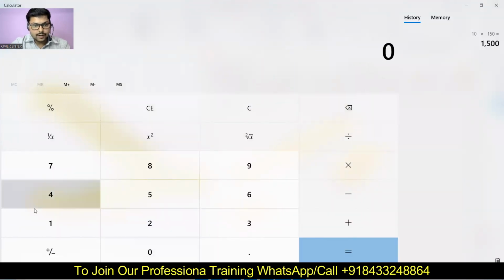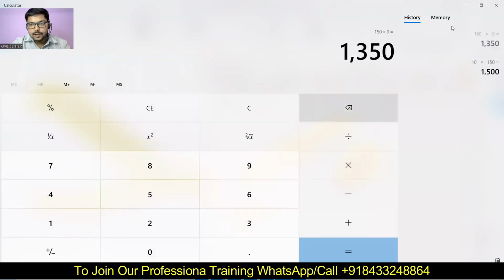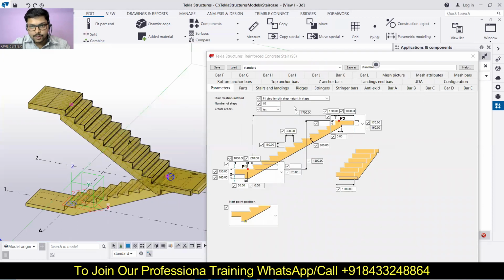Okay, so our risers are 150 and we have to multiply that by 9, so it will be 1350. So this height will be 1350. Okay, so click on No, and this is 1350. Yeah, this we can change. This should be 150, this should be 300. That is good. Over here it will be 100.